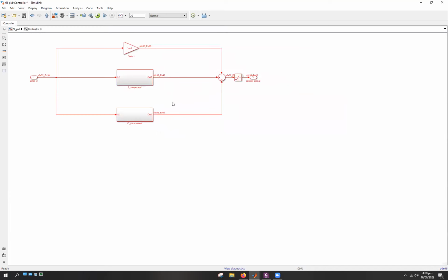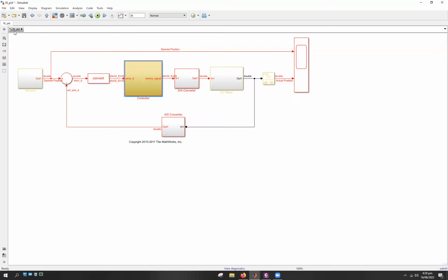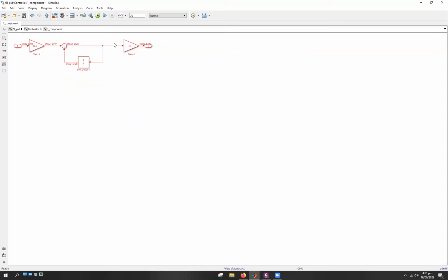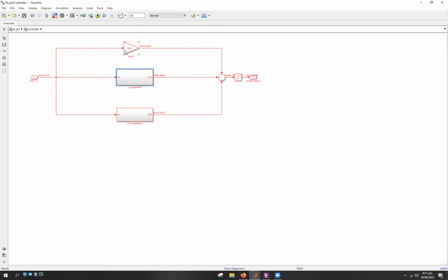So you have to either go through the manual to verify how the HDL compatible blocks work, or you will have to simply do trial and error. It's better that you identify which blocks are HDL compatible and then design your model accordingly. For the controller part, they have implemented the PID controller, and all of these blocks that you are seeing here are HDL compatible, meaning we can generate compatible HDL code for these blocks, and the code or the bit stream that we have generated can be deployed on the FPGA to perform the in the loop testing. Right.